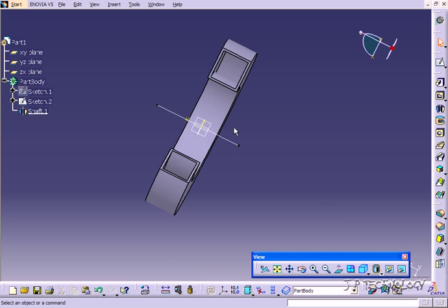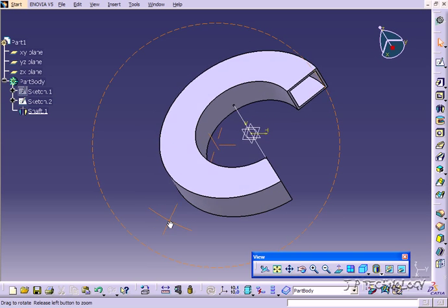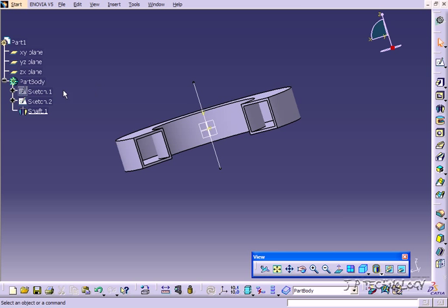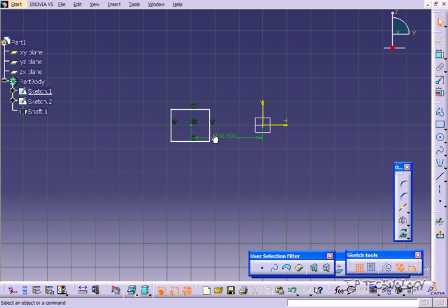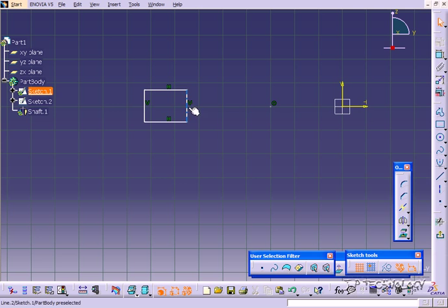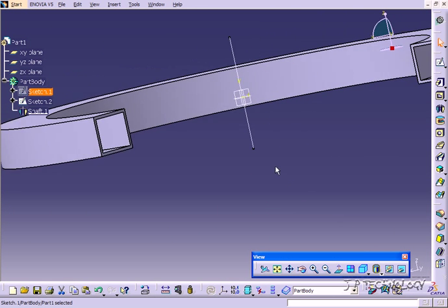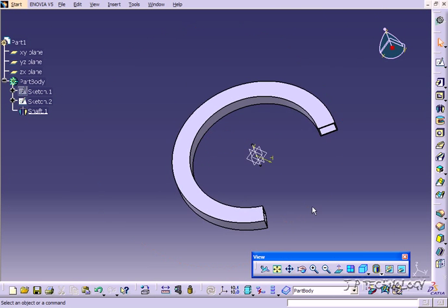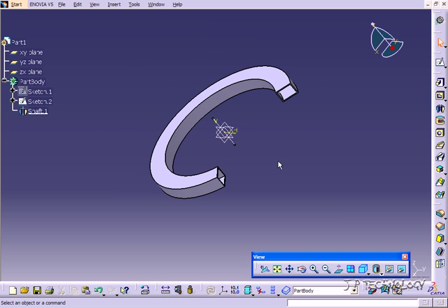And you can see that it rebuilt with the square rather than the circle. Now if we go back into the sketch again, let's move this square farther out, delete this dimension here, click rebuild, and now our entire shaft is larger and it's been extruded out more.